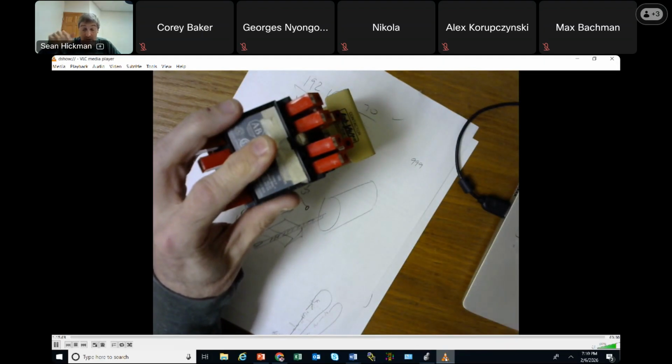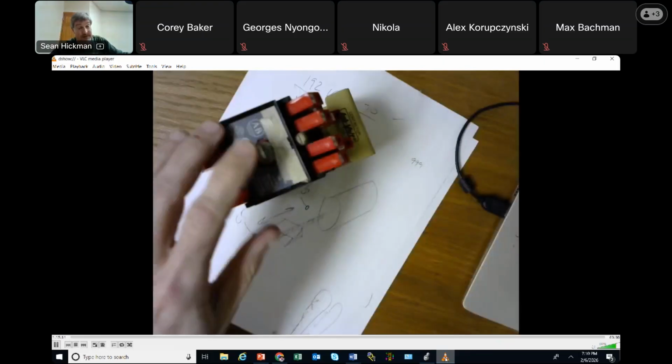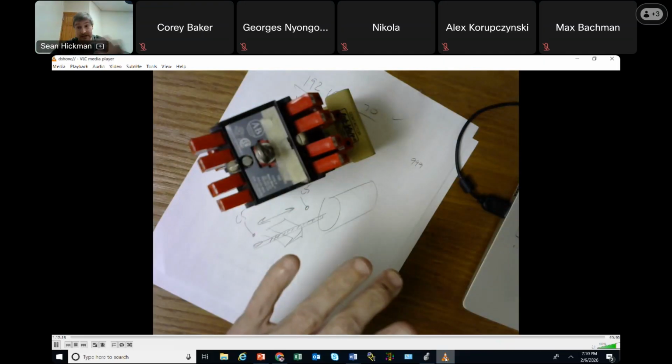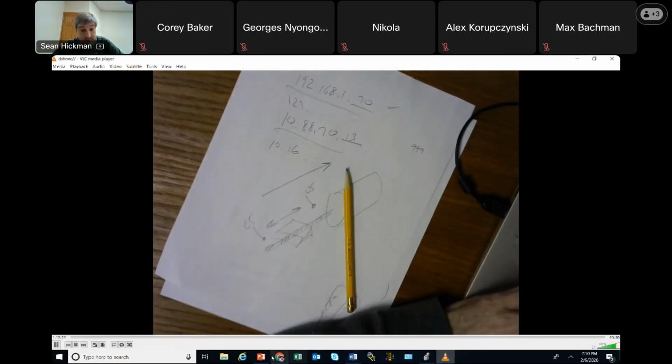And see, clockwise, is it going clockwise? It's going the wrong direction. You got to switch some leads, or you got to wire something up so that when you push the forward and the reversing motor starter, it's going the direction that you want, or you're gonna struggle.